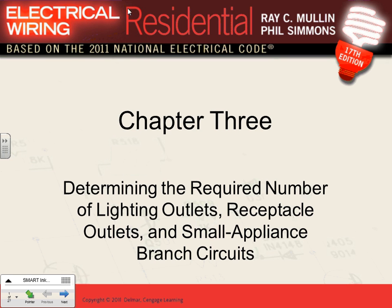As you guys know, we have an apartment building, and we're supposed to provide receptacles and lights for these habitable rooms, right? Based on the code and sound engineering judgment. I want to remind you guys, when we do that, we're going to do it based on the code and sound engineering judgment. Sound engineering judgment means if the code does not require it, and it's a good idea to have it, we're going to have it. But at least we're going to meet the code first.